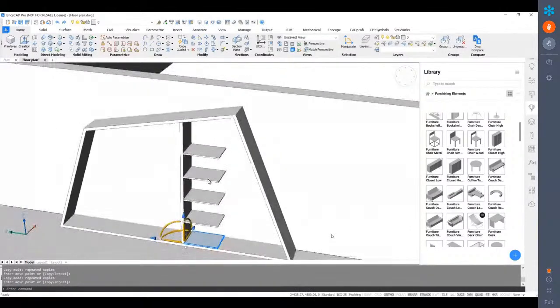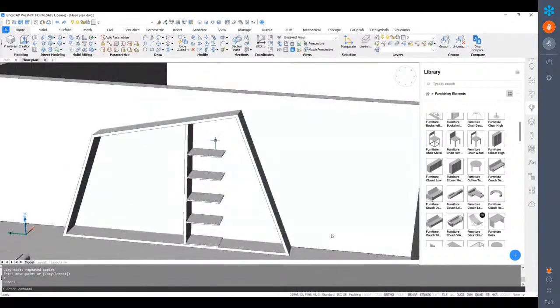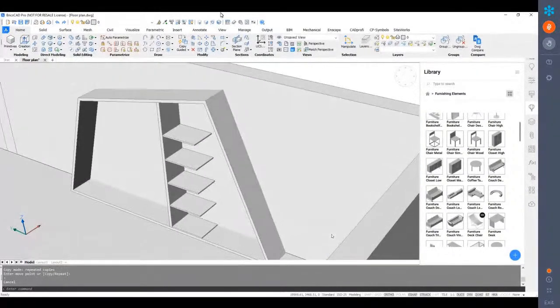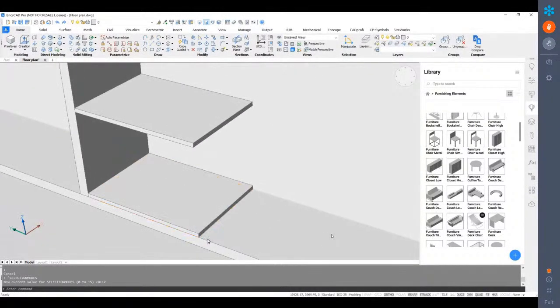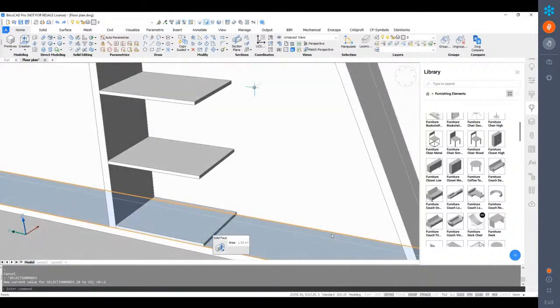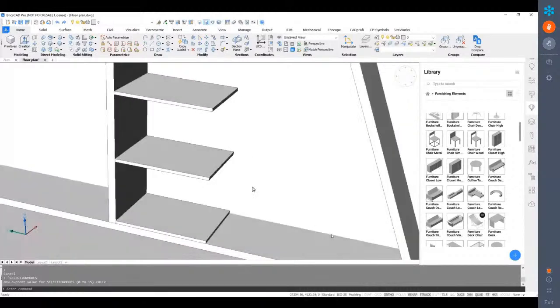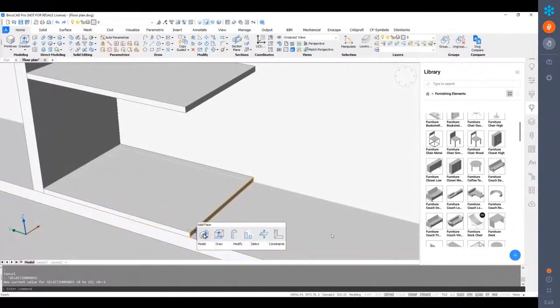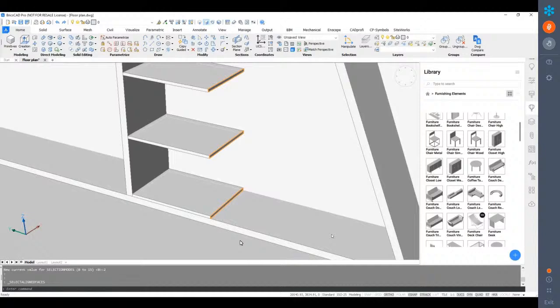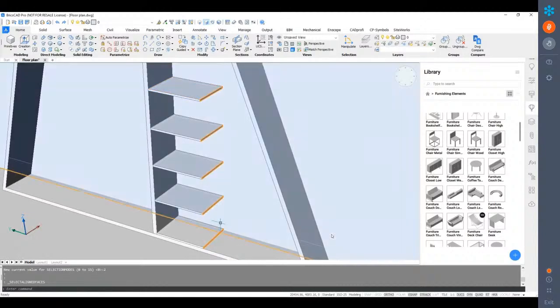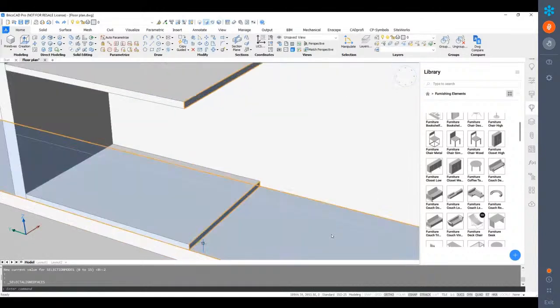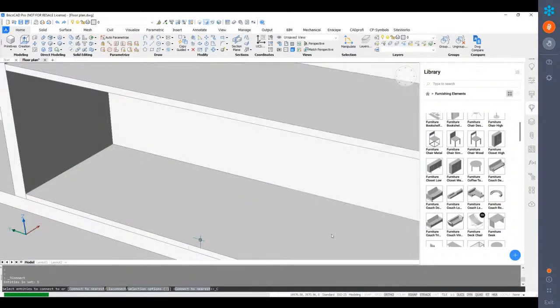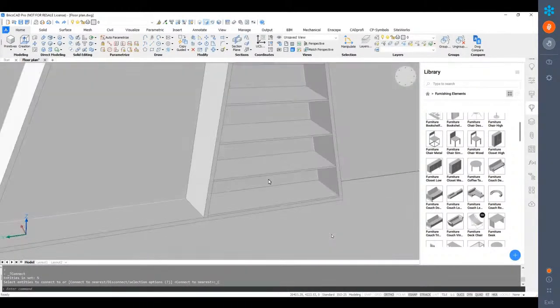Okay, so that's pretty good. At least I have something there, maybe for some displays. And let's just have this close up here. So again, we have something of a slant here to connect all these shelving to. And what we can use is actually something that comes just before connecting views, which is to select all the aligned faces. So once I select all the aligned faces, I can immediately select all these without having to go through them one by one. And after that, I can immediately connect them to the nearest solid, which is the slanted surface on my right side.